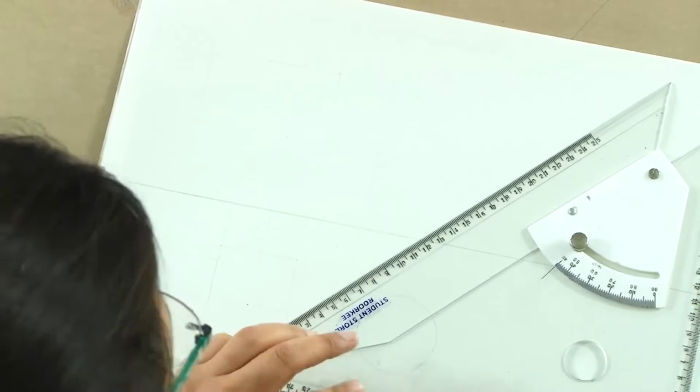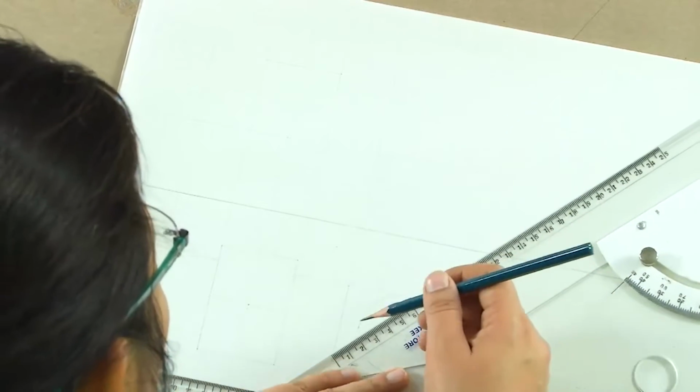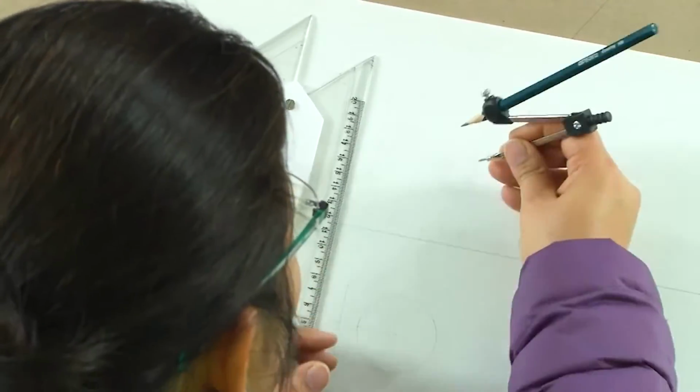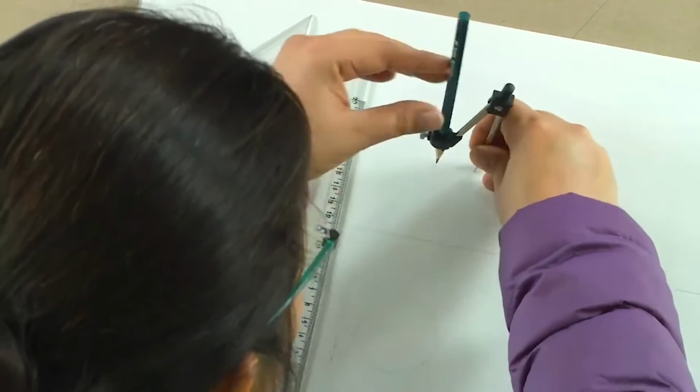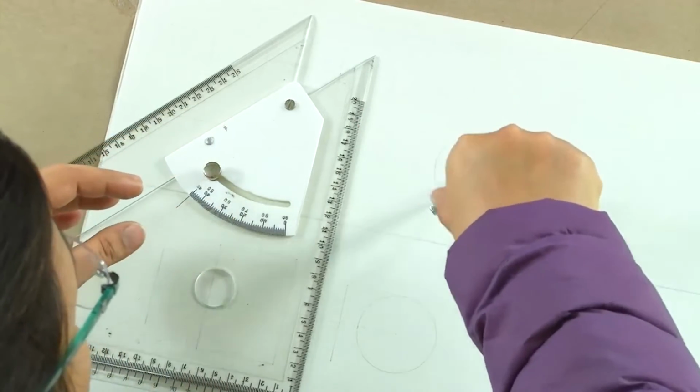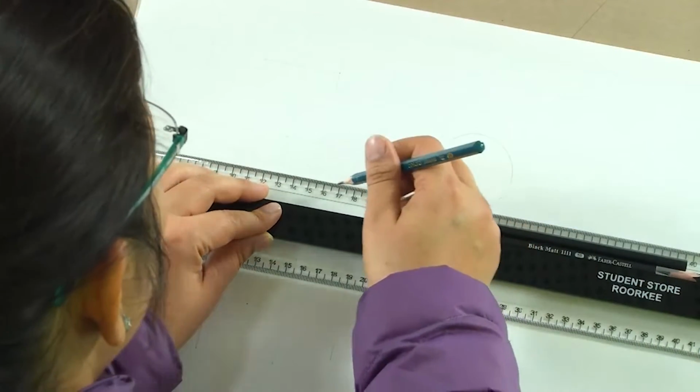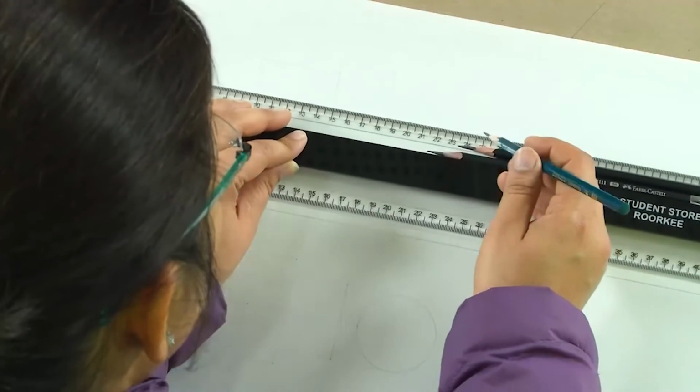Or what we could do, we could also take it to the side plane, which we also know as the profile plane. So, we may also take it up. So, this is what we are going to be seeing here, and you could also be taking the circle. So, we could be drawing the circle again using the center, or we could just directly be drawing the circle using its dimensions, the same dimension, but ideally we should be projecting it all the time, and then we just have to draw these lines which are passing.